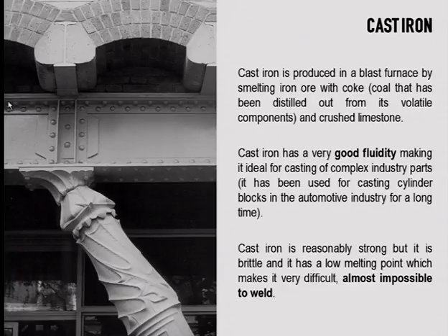So you see here again rivets. Very interesting that you see these masonry arches, and then they sit on these concrete pods. This white flange beam is actually a kind of lost formwork for those concrete pods. And then that's connected with these rivets and this plate to another beam. So you see how easy it is to shape this type of steel in different forms, or the forms you want. But again, no possibility to weld.